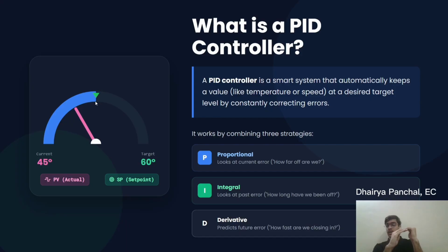And as the value goes above 22 degrees Celsius, which is not your set point value, your system will start once again to go to the set point. So your system keeps oscillating around the set point value, but it necessarily cannot reach it. This causes unnecessary power consumption in the case of an air conditioner, which has to continuously turn on and off and on and off. This system is simple, but it is not ideal. So for that, a controller such as a PID controller is used.